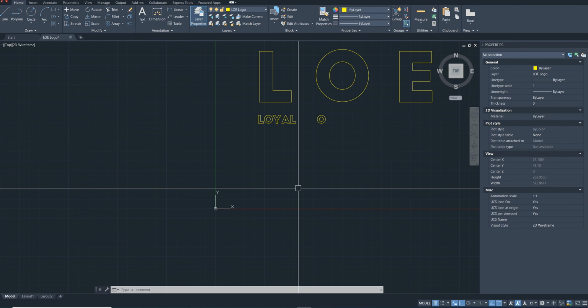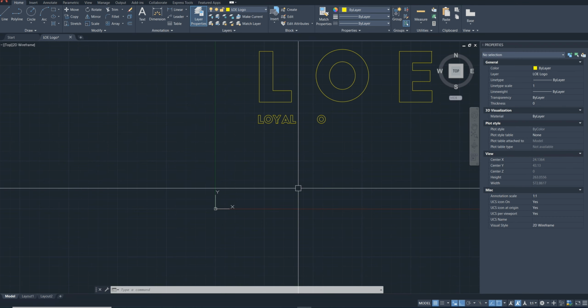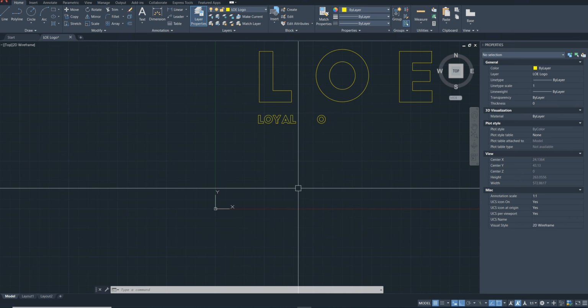And just another tip for you as well, if you do lots of CAD within the construction industry, it's also very handy when it comes to bolt holes and stuff like that. Doing fabrication drawings, it makes the process very easy when mirroring. So let's say you have a set distance between two bolt holes in a piece of steel, for example. It's very easy, just mirroring along that line, copying and getting two bolt holes. It's a very effective way of working within CAD that saves a lot of time.